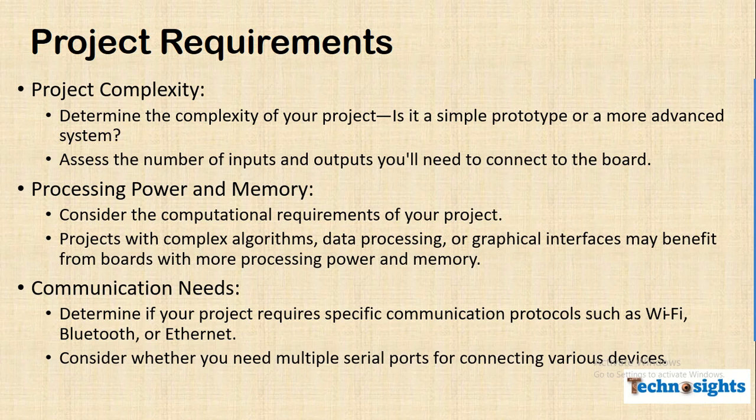Next aspect is the communication needs. Determine if your project requires a specific communication protocol such as Wi-Fi, Bluetooth, Ethernet, GSM. If such communication protocols are required in your project, you need to decide the type of Arduino board that is to be used. Then consider whether you need multiple serial ports for connecting various devices. Devices like LCD, LED can be connected with the Arduino board. So we need to check whether serial ports are available for that particular Arduino board or not.